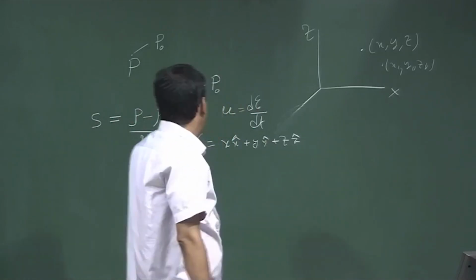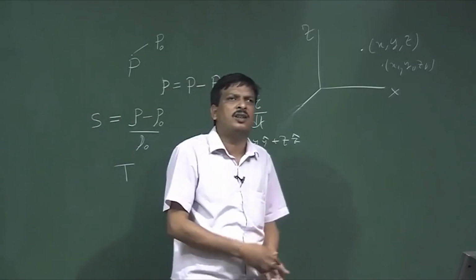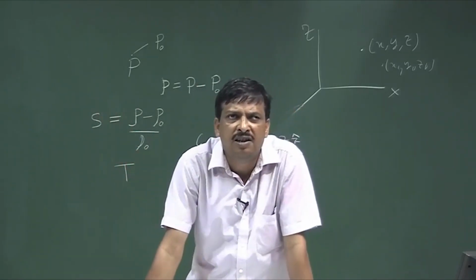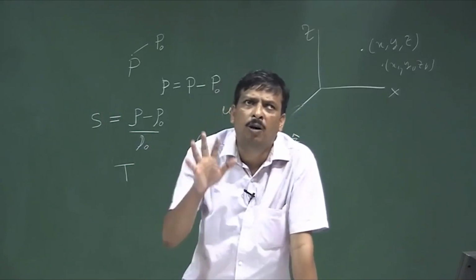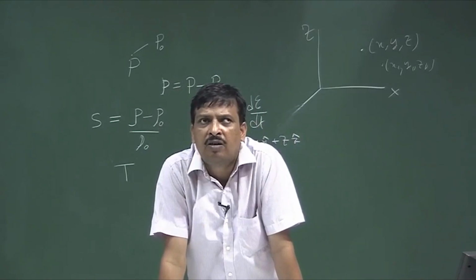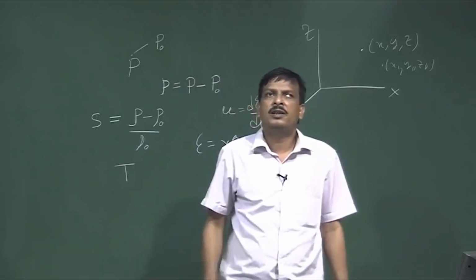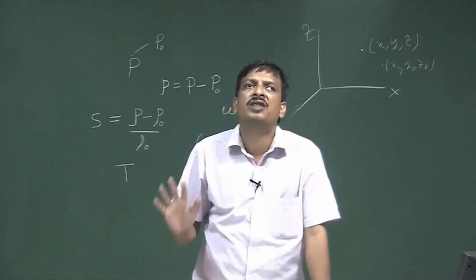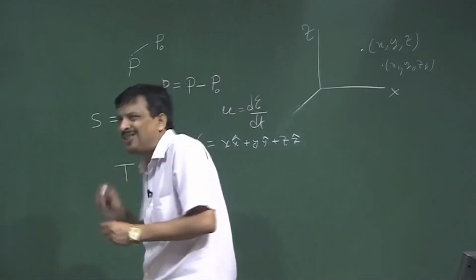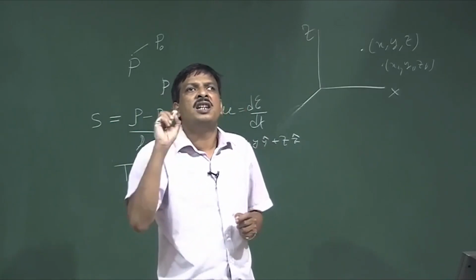Next is temperature. Think about the practical scenario: when the wave is transmitted, is the temperature changed? If it supports the linear wave equation, we said this transmission is an adiabatic condition. So, that means if an acoustic wave passes through a medium, the temperature of the medium does not change. The temperature is constant, so that means the process is adiabatic.